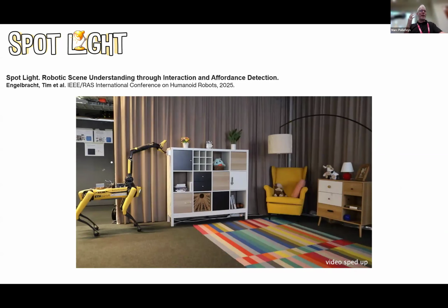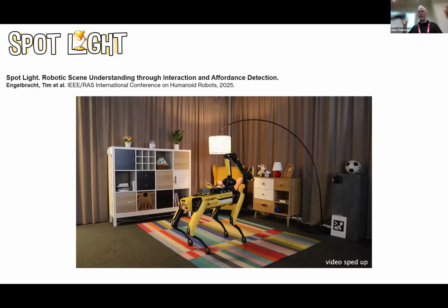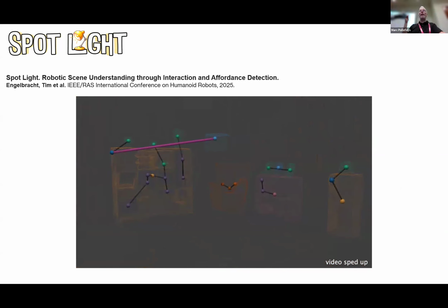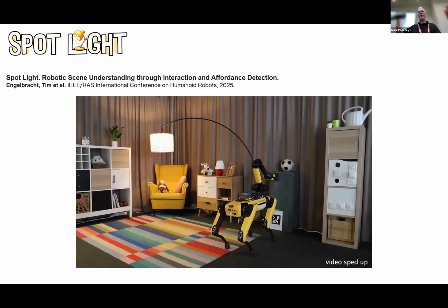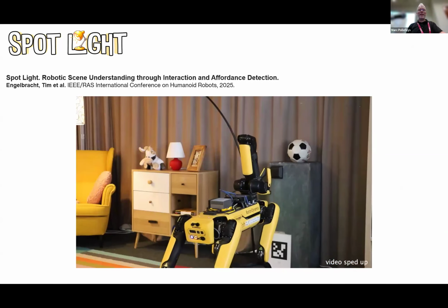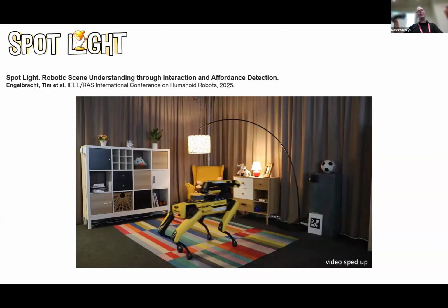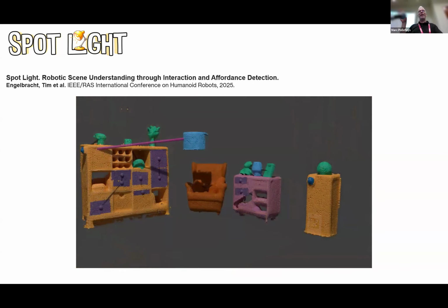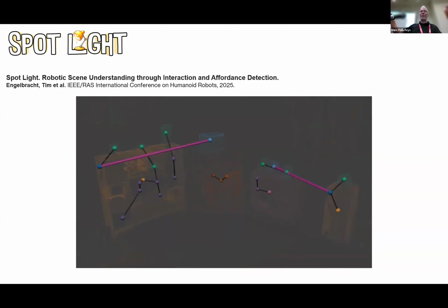And so we have the robot go and explore the space. It goes, presses a switch, and then checks which of the lamps are switched on with this switch. That allows us to update the scene graph and put a functional relationship between that switch and that lamp. We know roughly where the switch is from the initial mapping, and whenever we go there, we do a refinement to press precisely, so that we don't have to do it open loop. We go close to the switch, redetect the switch, and then press the switch.